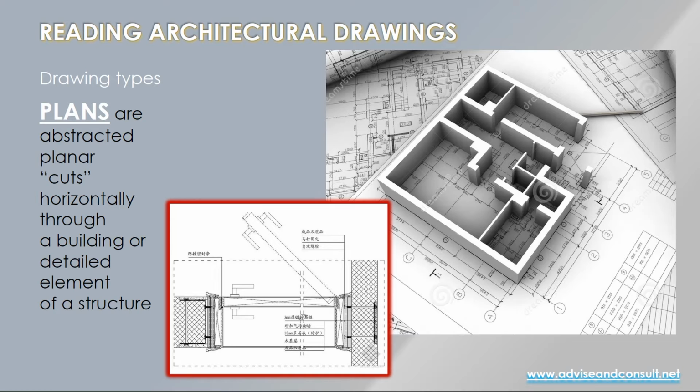So, for example, if the dashed lines were not there showing how the door moves, you wouldn't necessarily know where the hinge was and which direction the door opens in. And that can be very important for things like ADA clearances and hallway widths and passages where the door could swing out and hit somebody in the face.